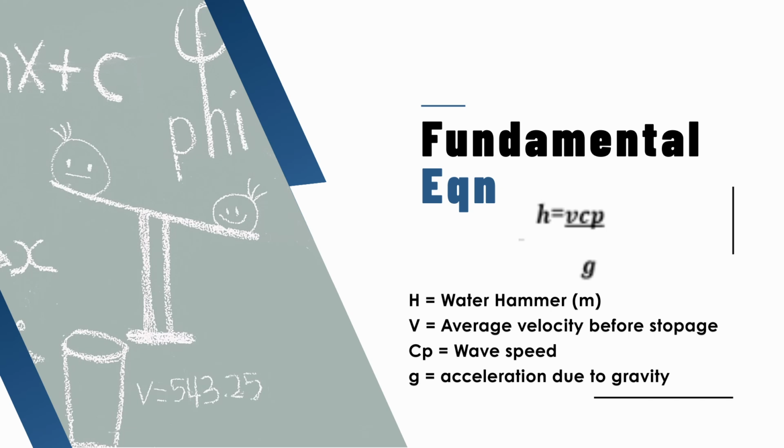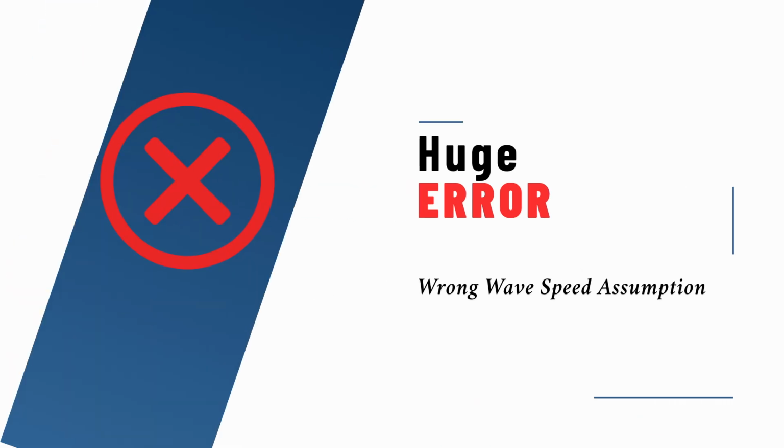So when we're doing this optimization, we have to take care of all these parameters to make sure that our system performs well. From this equation, I want you to notice something very important. The surge pressure depends directly on the velocity change and the wave speed. And wave speed depends on fluid compressibility, the pipe material, and the pipe wall thickness, as we're going to look into in our example.